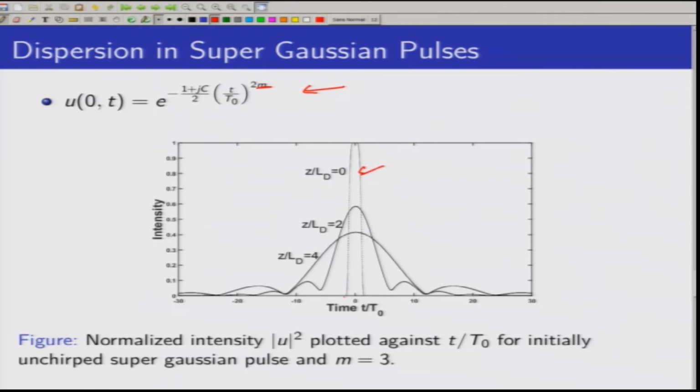As you can see, it is much steeper than the secant or the Gaussian pulses that we saw before, and the instantaneous frequencies get really high, because there is an instantaneous jump at the edges. So, there is much more distortion here. As the pulse propagates into the fiber, the trailing and leading edges start distorting, and the pulse starts losing its shape. In a communication system, this would be very problematic for us. So, it is really important for us to study these effects and to find techniques to mitigate them.